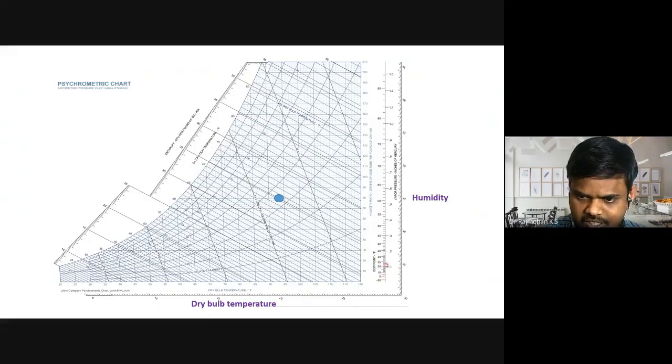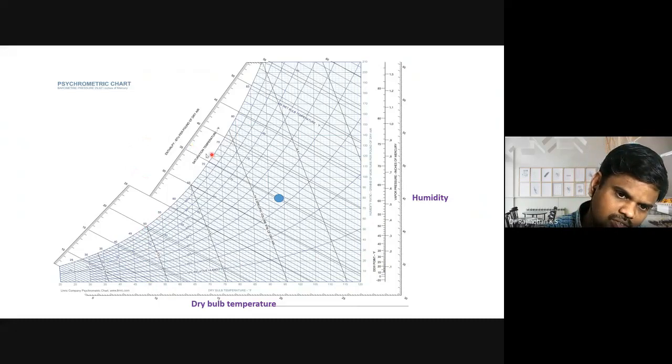So you can see the scale being given here for dew point temperature. Dew point temperature is the temperature at saturation when you are cooling something. You can see 50 is the wet bulb temperature, but the corresponding temperature on the x-axis is going to be the dew point temperature. Okay, then we have this enthalpy data here. So we can have an enthalpy diagram.